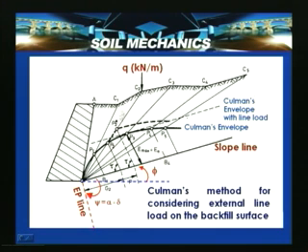Then an average angle alpha can be considered, and we can plot the weights of these wedges on the slope line, and then draw lines parallel to that pressure line, which is not exactly parallel in this figure. But when you draw, you will see that it cuts the potential trial wedge surface lines at points P1, P2, P3, P4 and P5, and at the point where this load is there, that hump will be caused, because of accounting for that load.